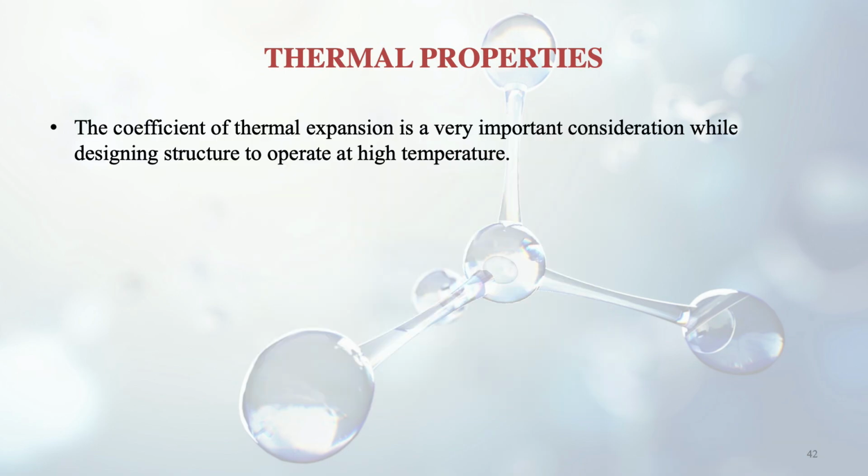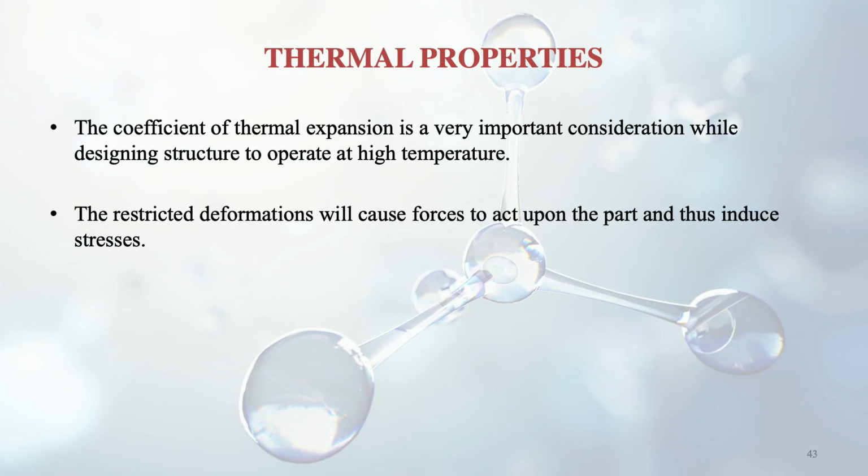The coefficient of thermal expansion is a very important consideration while designing a structure so that we can operate at high temperature. Restricted deformations will cause forces to act upon the part and thus induce stresses. When we heat a solid, it will expand. Suppose somebody restricts this expansion, this deformation. So what will happen then? Stresses will develop, because the natural tendency was to expand but it has been restricted, so stresses will come in.